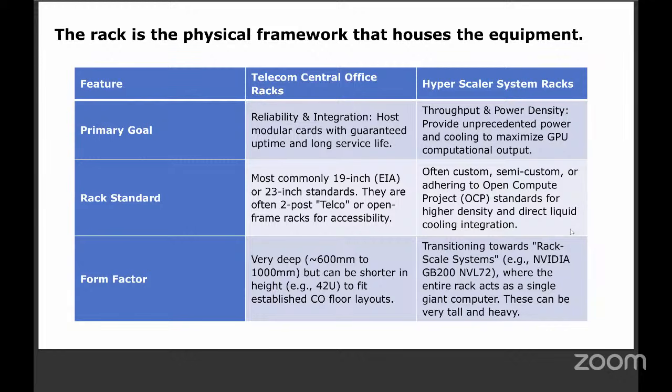Same as usual, for the picture I have shown, I made a table here: primary goal, rack standards and form factor. Primary goal, central office: reliability and integration. Host modular cards with guaranteed uptime and long service life. Redundancy is built in. Then we have generally a 19-inch rack. EIA is the standard. There is a standard company. Generally, it is called a telco, the telco for telecom operator.